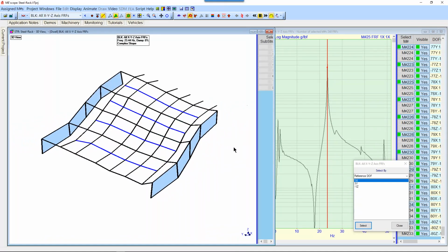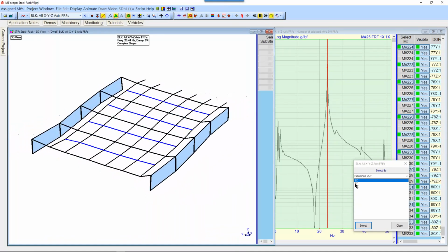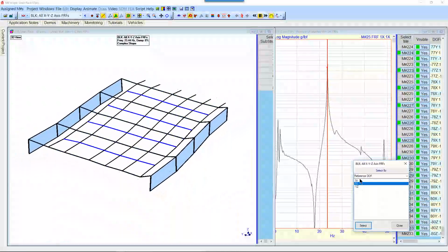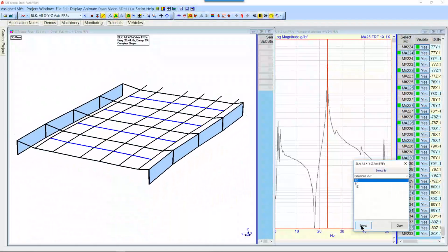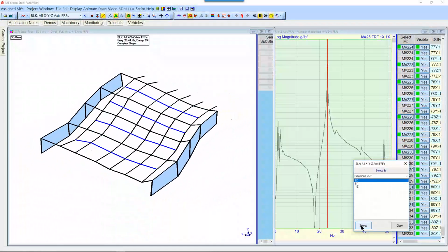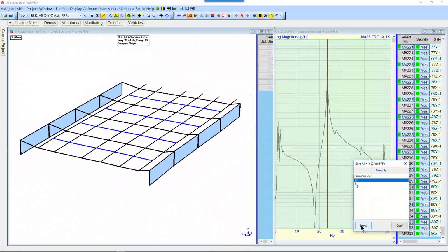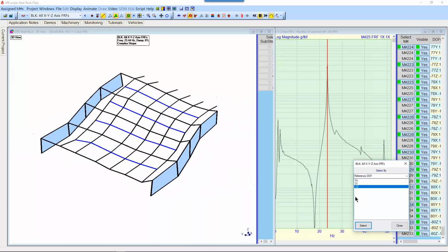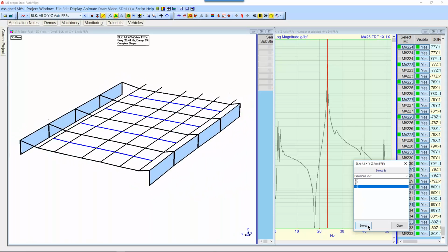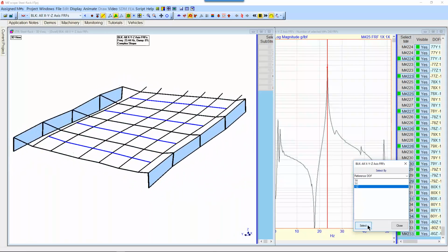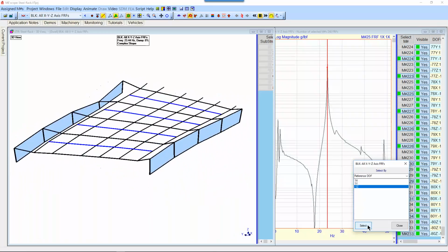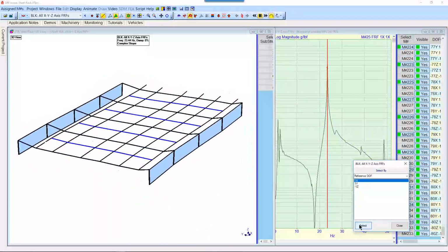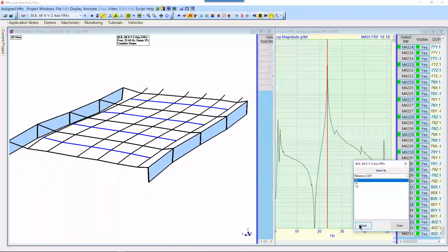There's my X direction. Now that certainly looks like a believable mode shape. Let me go to the Y direction. Still same mode shape. So if I switch references and I still see the same mode shape, that's an indication of a resonance. If it changed on me, that's an indication of an ODS, not a resonance, maybe more than one resonance. There's a Z direction, not bad, still the same, although the Z, because of the dominant motion of this mode, it's mainly a horizontal mode.